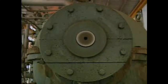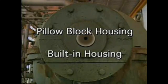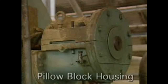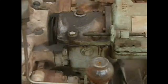Bearing housings are divided into two types: pillow block housings and built-in housings. Pillow block housings are located outside the machine casing and are separate from it. In some cases, the pillow block housing holds the end of the shaft. In others, the shaft passes through the housing.